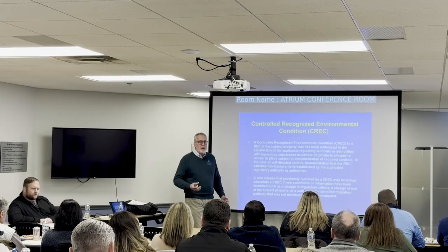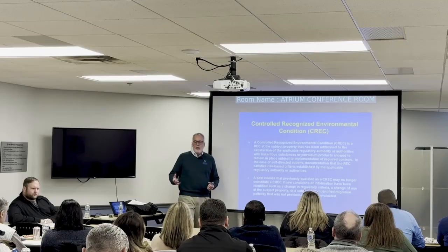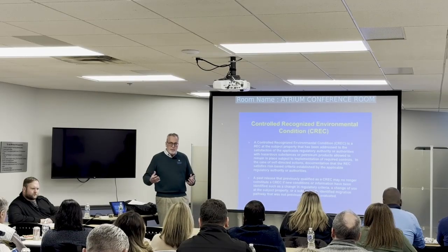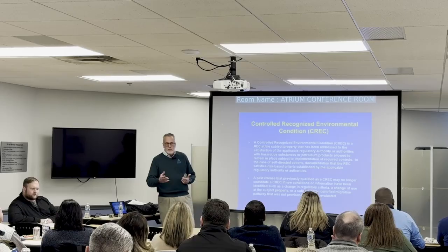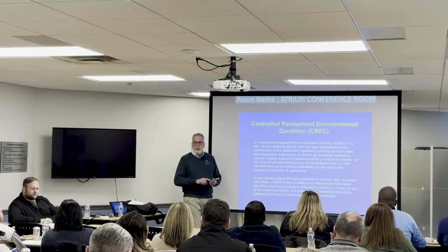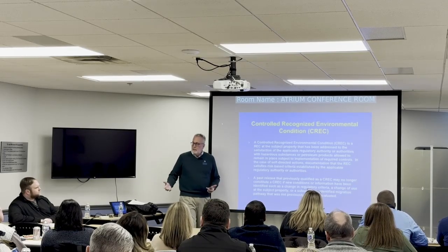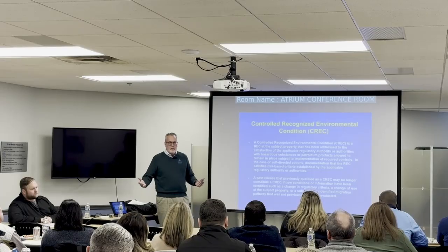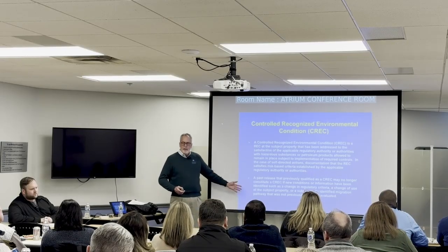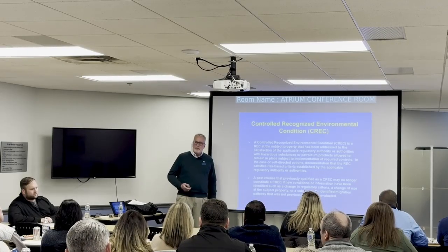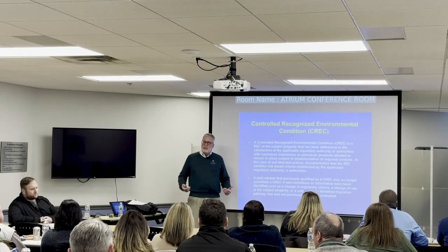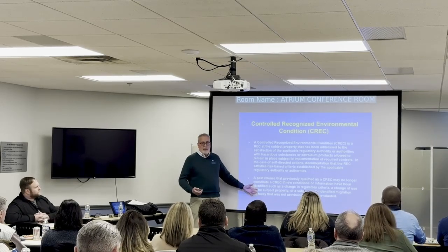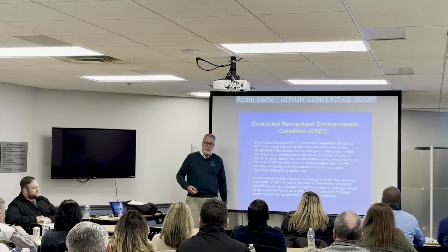The other problem is indoor air. In 2016, Ohio EPA published their standards for vapor intrusion in buildings, primarily looking at chlorinated solvents, which is perchloroethylene, tetrachloroethylene, which is dry cleaning solvent, and trichloroethylene, which is probably the best solvent known to man, and it's been the most expensive chemical probably ever used in history from a remediation standpoint too. They're both bad actors. But we really weren't looking at that vapor intrusion exposure pathway until about 2016.